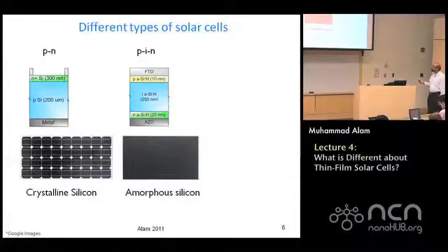In many cases, the thin film will look like this because it's roll-to-roll or essentially vacuum deposited. So it will look continuous. You cannot see it here, but there are stripe lines which allow them to connect it in series. So if it looks beautiful blue, then you know that's the silicon solar cells. If you have it like this, continuous, then generally that's more thin film like structures.